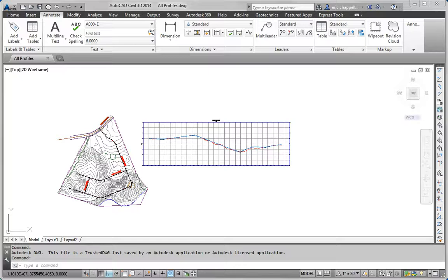In this exercise, we're actually just completing what we started earlier in the chapter. For the Madison Lane and Logan Court alignments, we're going to create a surface profile from the EG surface, then create a profile view for each one, create a layout profile, that's step 3. Step 4 is to round off the station and elevation values of each PVI to the nearest 5 foot.